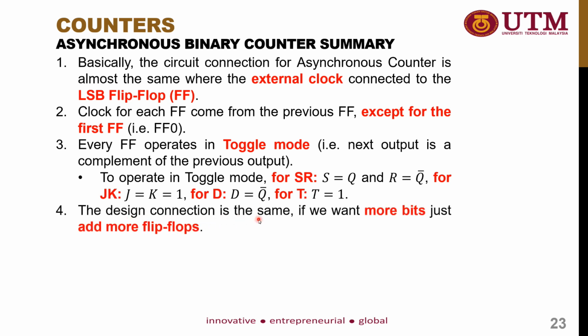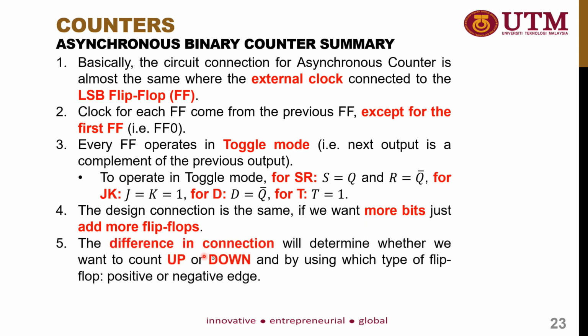So the design connection is still the same. If you want more bits, just add more flip-flops, as I've mentioned before. The difference in connection will determine whether we want to count up or down, and by using which type of flip-flop, positive or negative edge triggered. As I have already shown you in the previous slides, if we want to design a count up or count down counter, we need to define the type of flip-flop that we have, whether it is positive edge triggered or negative edge triggered, and then we can define the correct connection for the flip-flop to conduct a specific function, whether we want it to count up or count down.